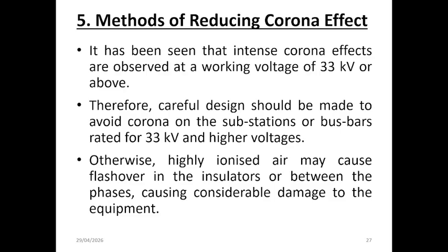Okay, this slide discusses practical methods for reducing the corona effect in high voltage systems, particularly at voltage levels of 33 kilovolt and above, where corona becomes significant. At these voltages, the electric field around conductors can exceed the critical value, leading to ionization of air and the formation of corona. Therefore, careful design of substations and bus bars is essential to control electric field intensity.